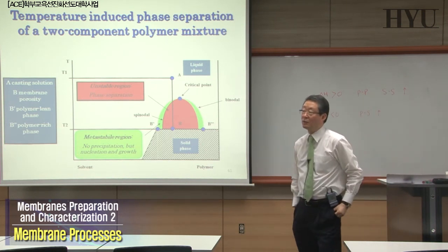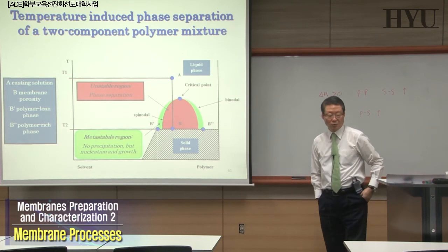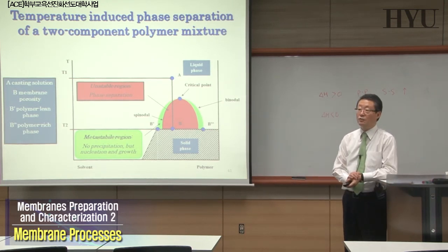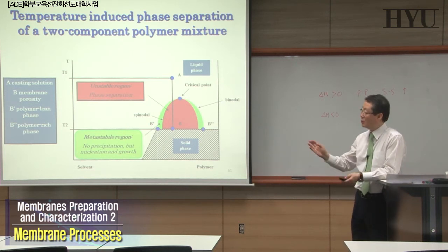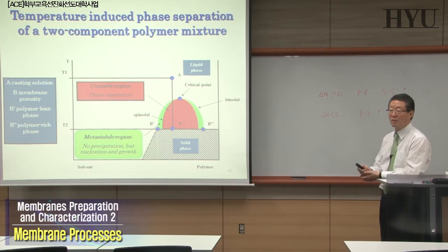So far, I think we talked about flat sheet and hollow fiber membrane systems, and we discussed the general description, particularly the phenomenological description of phase separation, particularly TIPS and NIPS, and the importance of macro void formation. Macro void formation is a kinetic factor, and the kinetic factor will determine the macro void, and the macro void will eventually affect the finger-like structure and the sponge-like structure in your membrane configurations. Okay? So we can further discuss the thermodynamics and the kinetic factors on Friday.